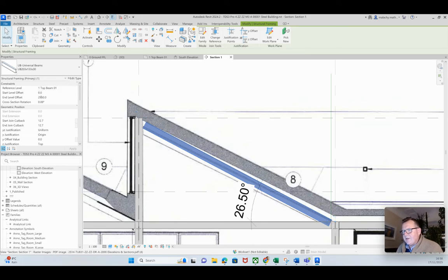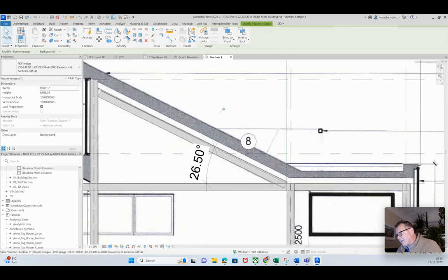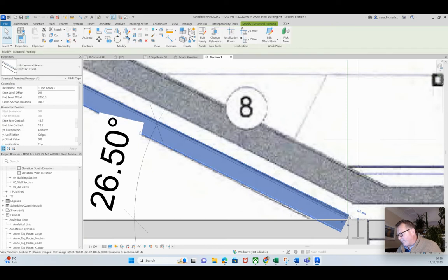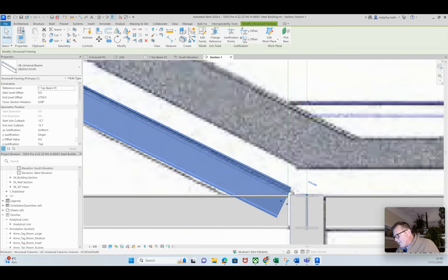So I'm going to bring this down to 2750, and that is more or less not far off. Okay, so has that moved there, I wonder? Let's see now. It didn't snap exact. Oh, there, it snapped from this point here. I probably should have snapped from where I created the reference plane.